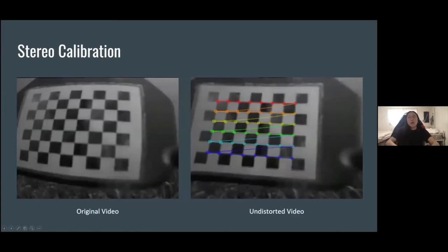Also, because we are using fisheye cameras, the objects and the signals are distorted in the videos. Therefore, after we finish the 3D coordinates extraction, we need to do the stereo calibration. We first calibrate the checkerboard and generate the map and apply the map to the video.